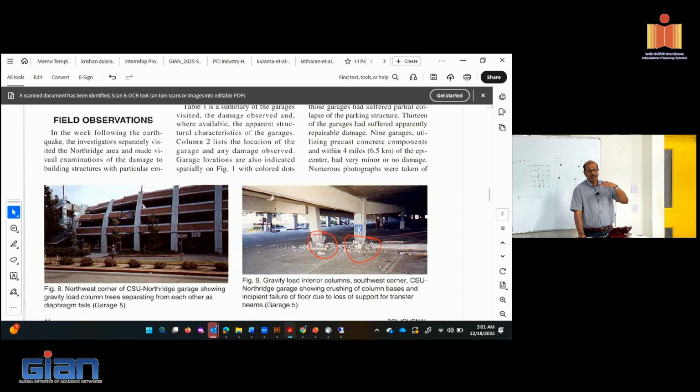In Kobe, there were actual buildings that went through earthquake motion. They performed reasonably well because the post-tensioning is pretty reliable. They're bonded, so it's very unlikely that you will lose it. But because of that plastification we talked about, the connection region did experience damage that they couldn't fix after the earthquake. So even though structures survive, just like cast in place, they have to take the structures down. And there were concerns about localized failure, because the spread of plasticity is not as good as what you see in a cast in place system.